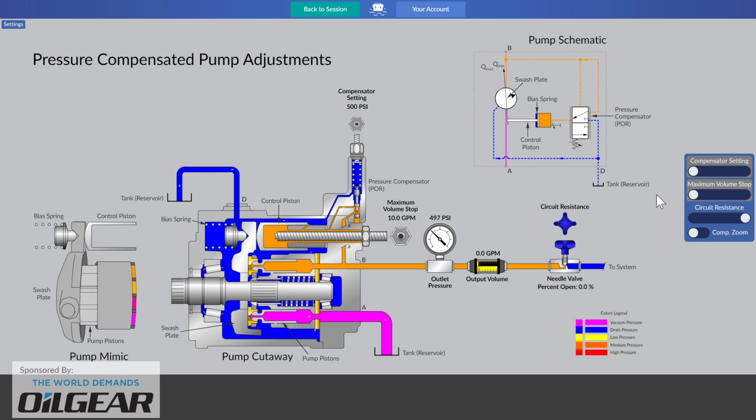All right, so if we want to make an adjustment, if 500 psi is not the correct maximum pressure setting to support functions of the hydraulic system, if the manufacturer of the hydraulic system requires perhaps that it be set at 750, we now simply need to very carefully turn, and now our pressure gauge should be following our every turn of the wrench, and it most certainly is. The pressure on the pump's outlet gauge is following the turns of the wrench. That's a good sign.